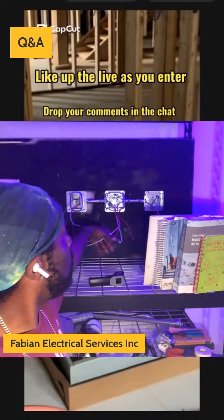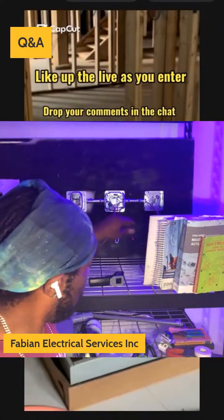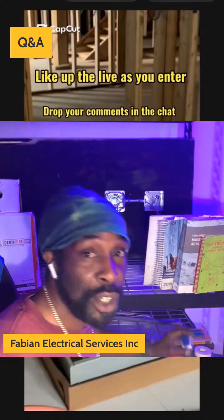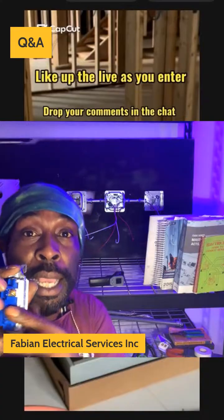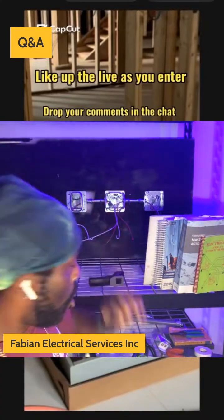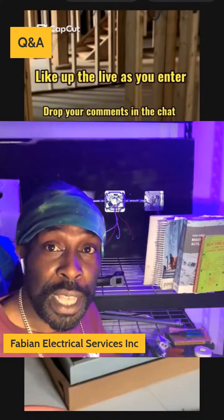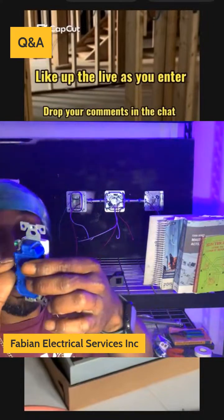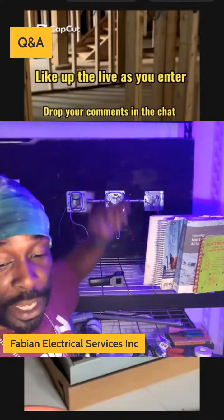Now when it comes to my wires here, if I'm going to be installing it on a switch, I'm going to go straight onto the screws instead of making connections into here. Or if it's a receptacle, I'm going to go right onto the screws instead of making connections here.